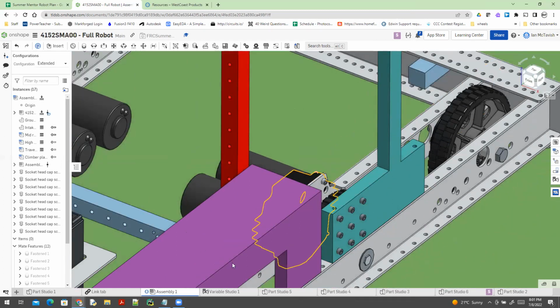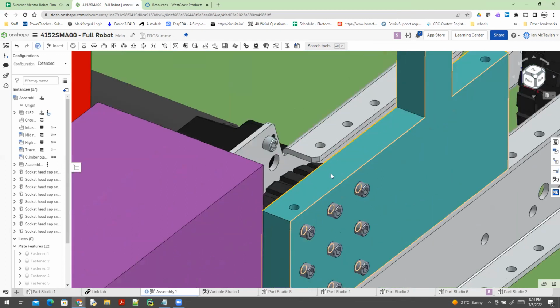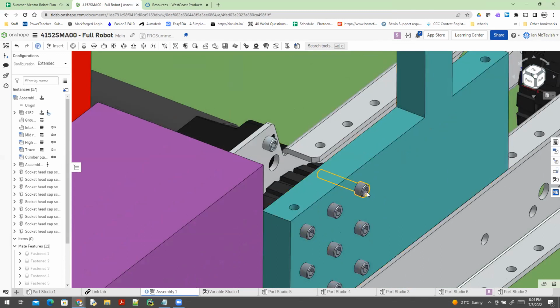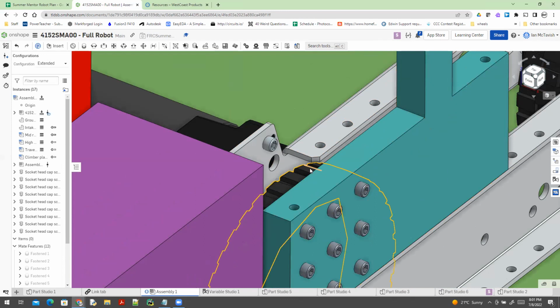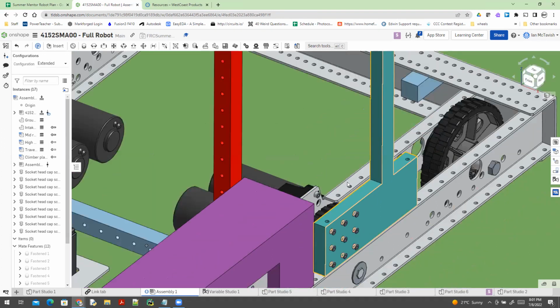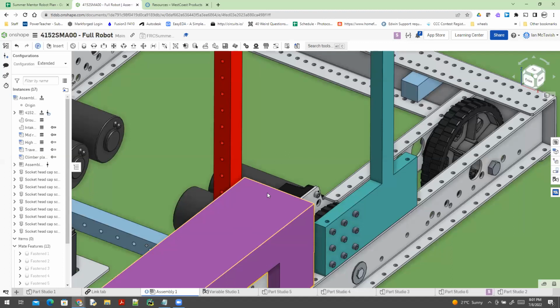And it's always think about, like, what tool do I use to assemble this? So here, Allen key, makes sense to put the Allen key where it's hard to reach, and the ratchet on the other side. So I'd have the nuts on this side, because then I can just Allen key in, ratchet, ratchet, ratchet, and get everything off really fast. So that kind of strategy of thinking about how it's going to hold together and how you're going to put it together is really, really crucial.